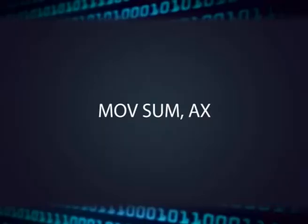In all memory reference move instructions, the effective address of the memory location is computed as the offset specified in the instruction, added with the contents of the data segment register, which is shifted left by 4 bits to make it a 20-bit address. Take an example where the instruction is MOV SUM, AX. In this instruction, the memory location identified by the variable SUM is specified using direct addressing.